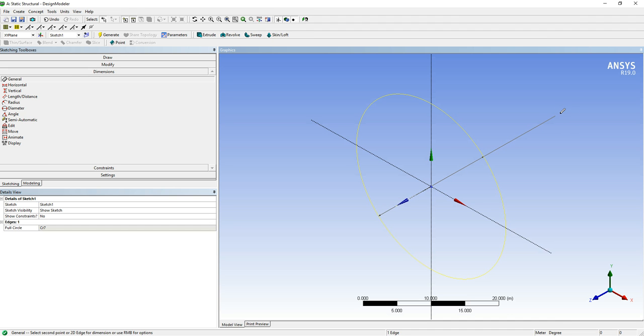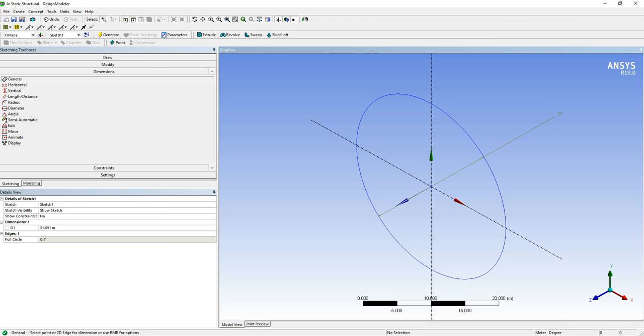Did the same thing, I opened it up, left clicked once. You'll notice now that once we've put that dimension on, it comes in as D1 on the front. Now you can change this, so if you go on to dimensions, go to the bottom where it says display. If I left click on there, you'll see it's got name or value. Personally I like to see the value. So if I click on value, I could drop the name if I wish and it would just give me